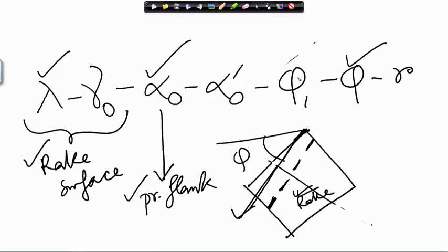After that, alpha 1 helps me define the auxiliary cutting edge position. Rake surface is not just this square, but it is extended to infinity in all directions. It is an infinite plane. From there, we are segmenting a small portion of it. So, this is the auxiliary cutting edge, and in the same way we define the orientation of the auxiliary flank by using up this information.